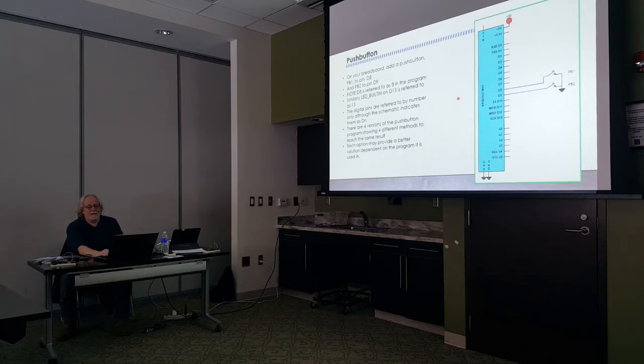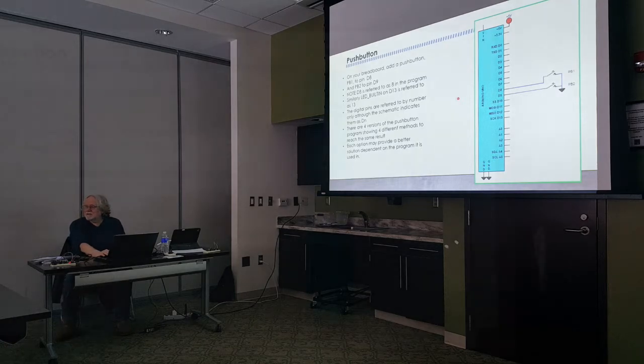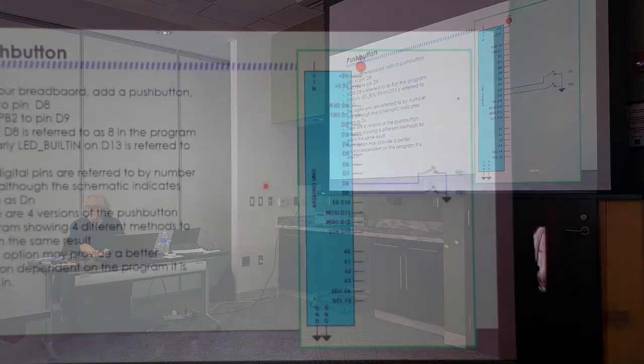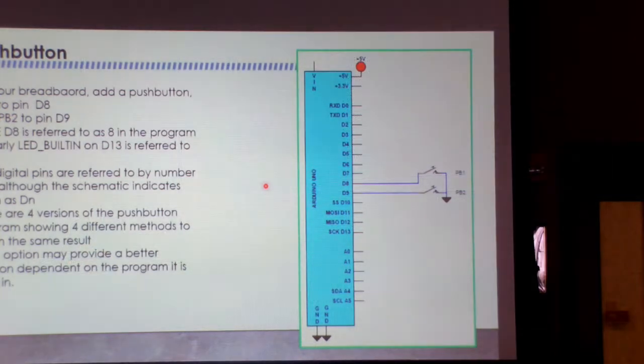No big deal. If you're a hardware designer, you probably say, where are the pull-up resistors? The pull-up resistors are inside the processor, and that was the input pull-up instruction. Turn that pull-up resistor on, so that you could have a 1. Otherwise, you had a 0, or maybe a 1, and maybe a 0, depending on how it's floating. So that's why you need a pull-up resistor.